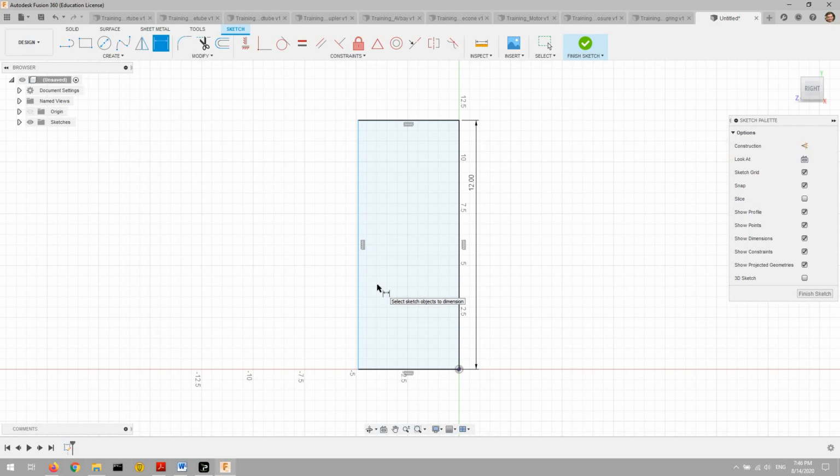To find that, you just subtract the diameter of the radius. Sorry. I did the math wrong, so it's not the number I just said. You subtract the radius of the motor enclosure from the radius of the outside of the rocket. So it's actually half the number that I just said. So pay no attention to the man behind the curtain.